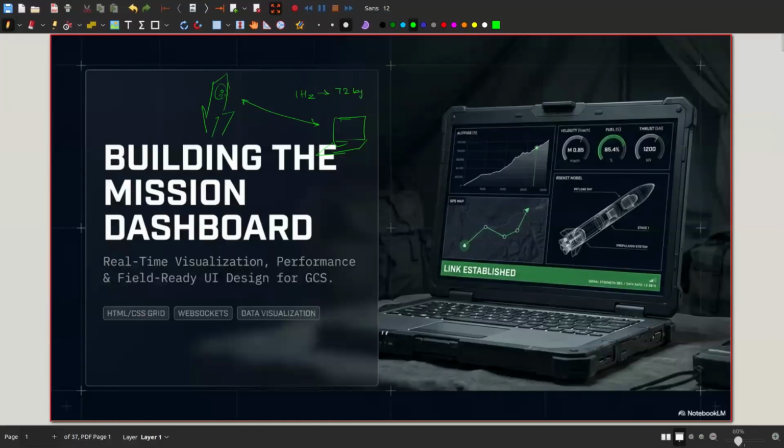You have to receive approximately 72 bytes of data, and it depends upon how many sensor values you have. Let's say you have time, altitude, pressure, temperature. So this value of 72 bytes can vary. These are merely bytes. Let's say you're receiving 72 bytes at the rate of 1 hertz, and the baud rate is set to 9600, or in most cases 115200. So this is the baud rate, this is the approximate bytes that you'll receive, and this is the frequency at which you're trying to receive these bytes.